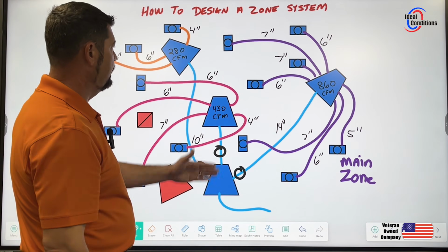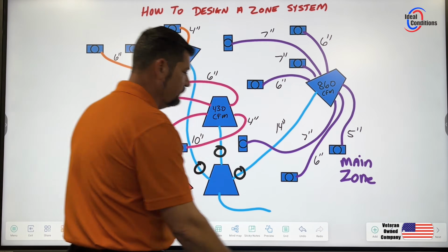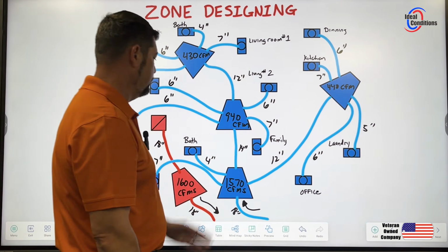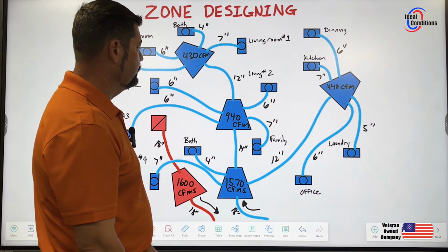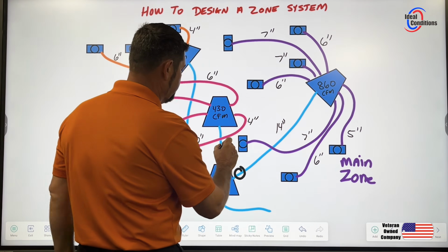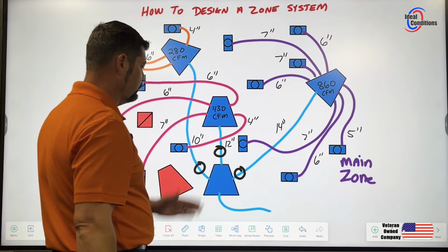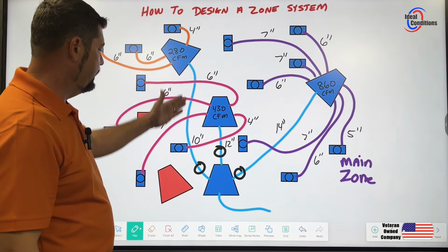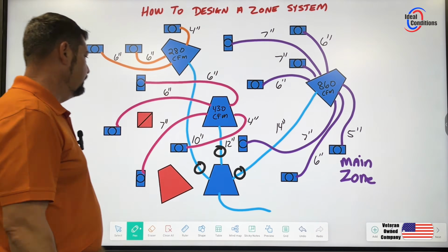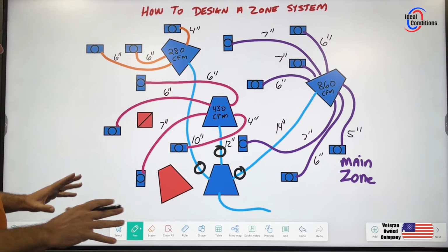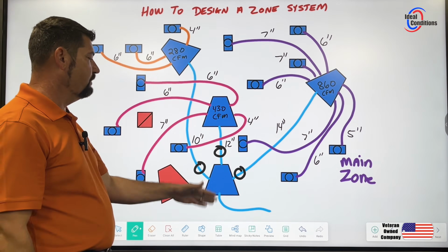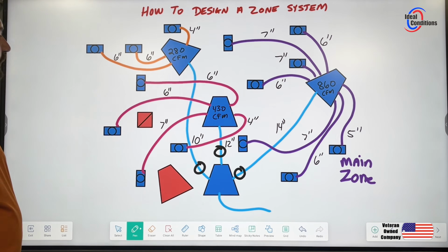Okay, what size trunk line do I need here? Well, what did we have originally? Will it work? Well, no, we had a 14 originally. So no, I'm sorry, that's not going to work. So we're going to have to size this as a 12. So we have a 12-inch trunk line, 12-inch damper. Over here, we have a 10-inch trunk line, 10-inch damper. And over here, we have a 14-inch trunk line, 14-inch damper. So we just rearranged where the takeoffs were going on different boxes, replaced the trunk lines, rerouted them back to the main distribution box. Everything else is just a normal mixing box here.